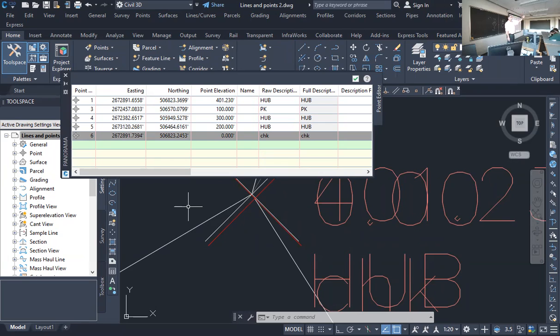If you just want a horizontal error, inquiring a CAD distance is going to give you a 3-dimensional error. How do you get a horizontal error? Well, in CAD, sorry. Oh, I was just going to do trigonometry. You could, and I know you all have the skills to do the trick, right? I have every faith in, okay, I have an X coordinate and a Y coordinate, and square root of X squared plus Y squared. Okay.